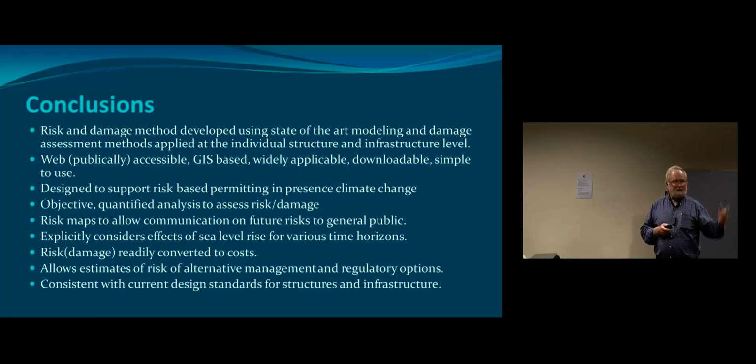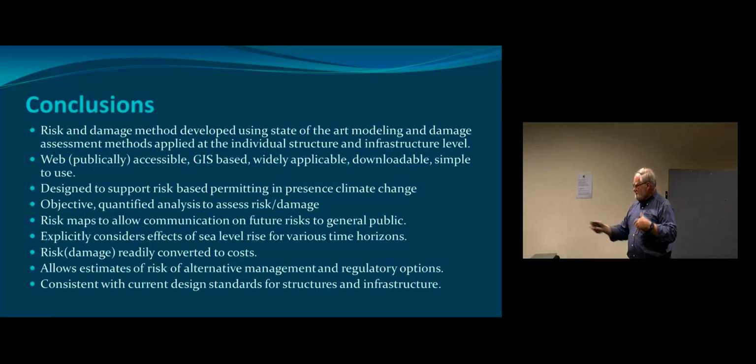Essentially, design life permit-based. It's an objective analysis, right? You quantify the uncertainty in it as well. That can give you an estimate of lower risk, the upper risk. You can essentially see what your risk tolerance is at sea level rise. The maps that I showed you have proven very effective at communicating this risk. There's an explicit consideration of sea level rise, and the one that you pick, you can pick the 100-year and 2 feet of sea level rise, which makes you think that you're going to do a 50-year kind of return period or 75 years. So it allows you to sort of explore what those options are.